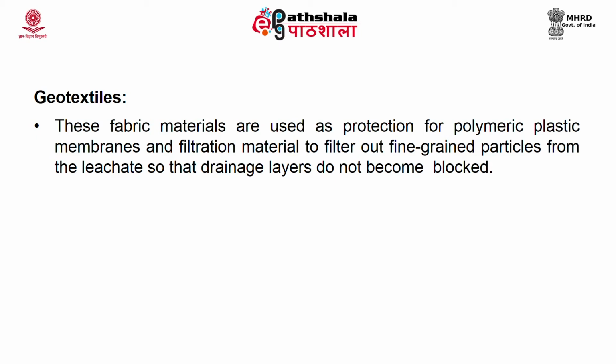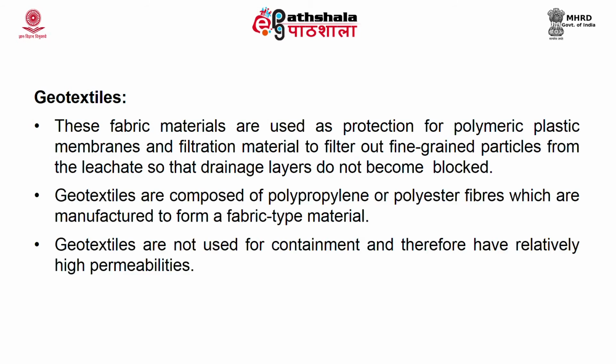And what are these geotextiles made of? They are generally composed of polypropylene or polyester fibers, which are manufactured to form a fabric type material, and they are not used for containment and they have relatively high permeability. I told you they are not used as a liner material, they are just used as a protection material for this liner material. Hence, it is not necessary that it should have a low permeability, they have high permeability.